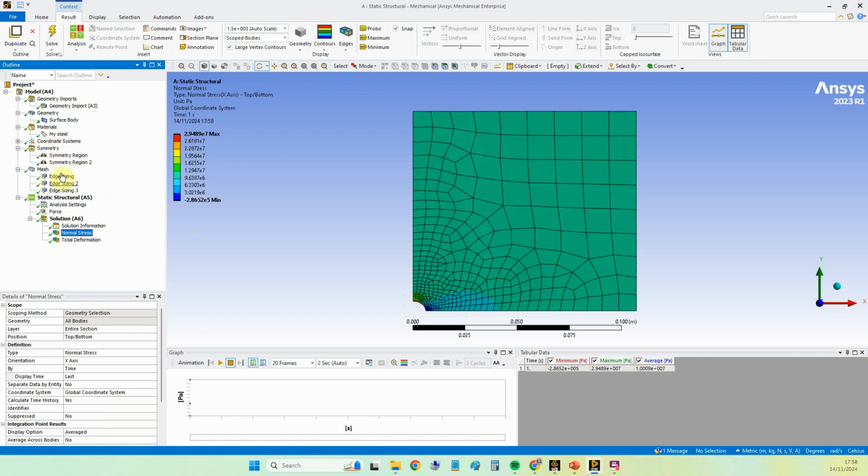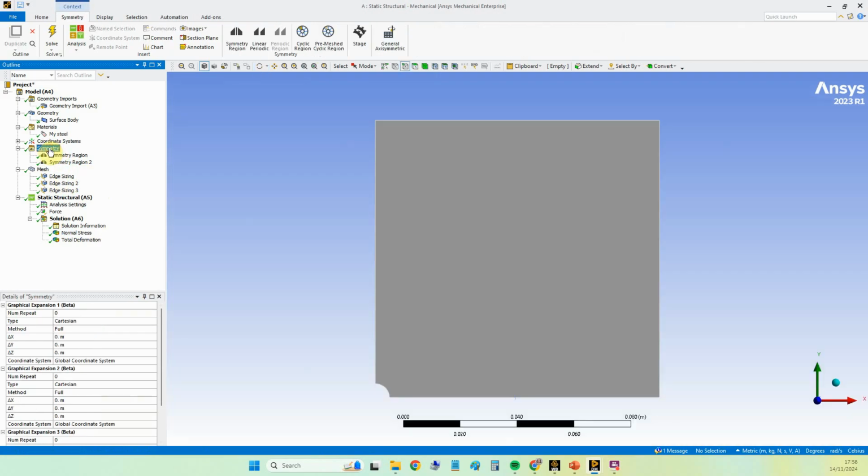So we can just go back into symmetry here, click on this. So again, I'm going to follow the same methodology that I did before. So I'm going to say I want, first of all, two versions of it. And I want half, and I want you to reflect across the x-axis, and so I'm going to use a very small number in there, 1e to the minus 6.